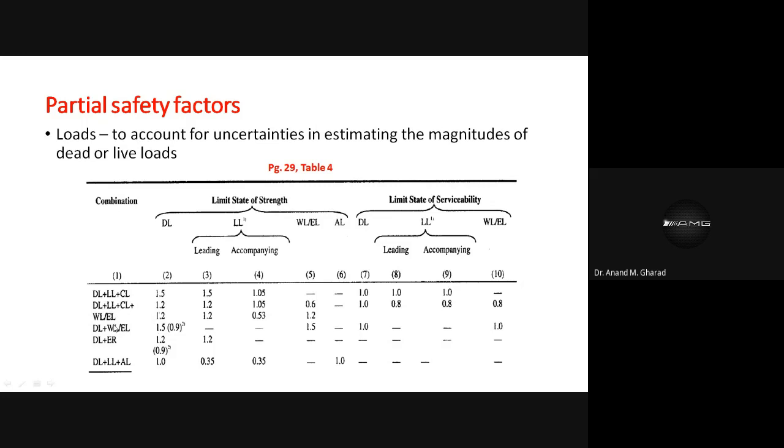Yes, sir. Okay. Similarly, dead load plus minus wind load or earthquake load, dead load plus erection load, and dead load plus live load plus accidental load. The accidental load and erection load combinations are not used frequently, in the sense they are very specific and condition based. Therefore, we will not make use of these. We can see the usage of the first three combinations.